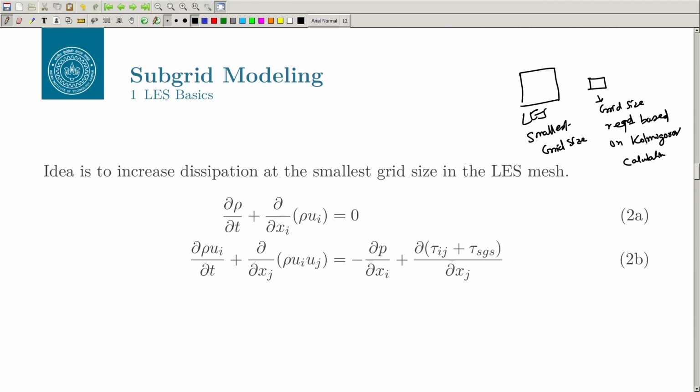We have discussed what is the grid size that is required, and the dissipation happens at this scale. This is what is going to dissipate. This is where it is going to break down. This is what is going to dissipate into heat, but your grid size is this much, right. So, we want the same dissipation which was happening here through the mechanism of the natural viscosity to happen here also, right. So, what we will do, we will follow the logic that we had from RANS.